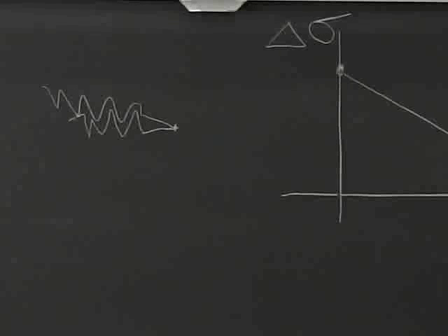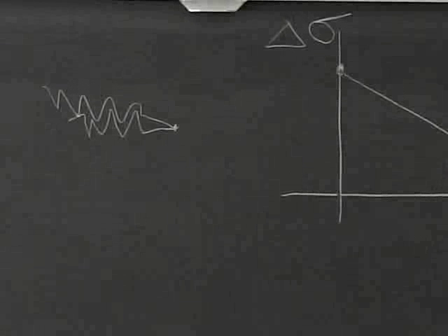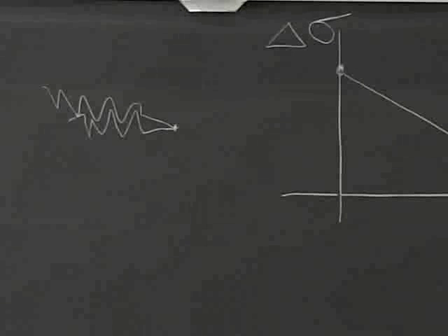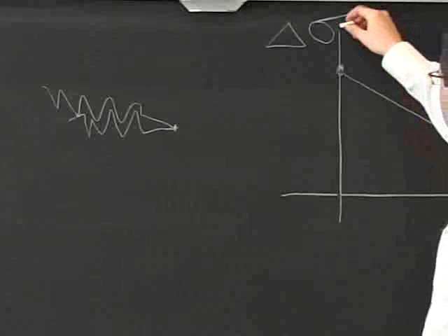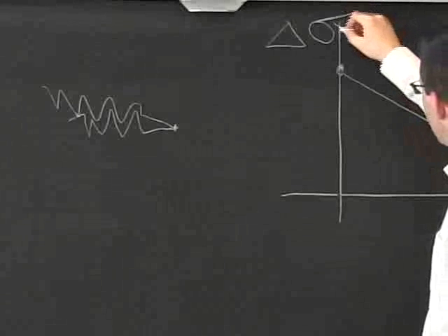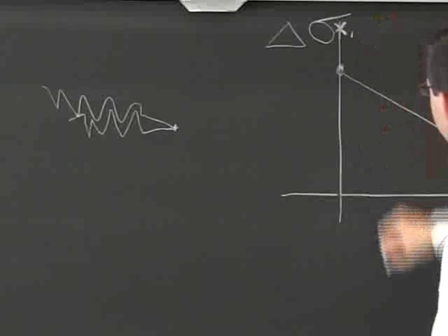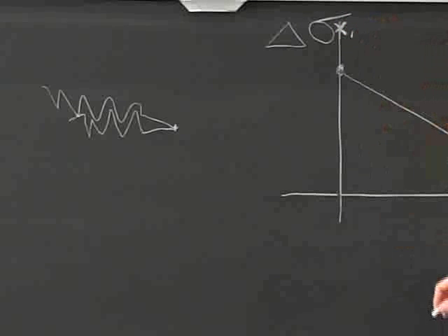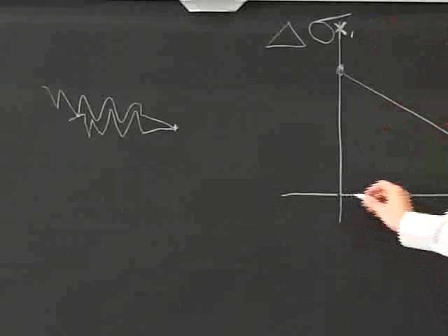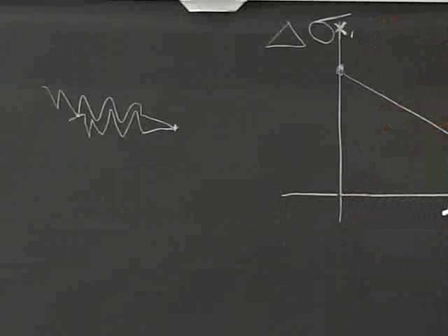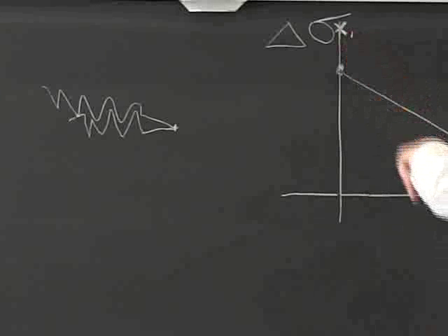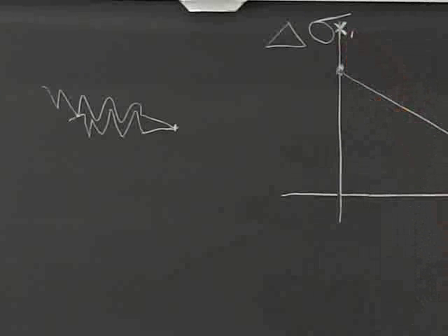So I introduced this concept here of Goodman for bolts, because that's where it's used a lot, because we preload the bolts. So instead of loading the bolts, the example I introduced over here, this would be a condition 1. What you do is you preload it to about 80% of the yield, and your amplitude is going to go down by approximately a factor of 7.